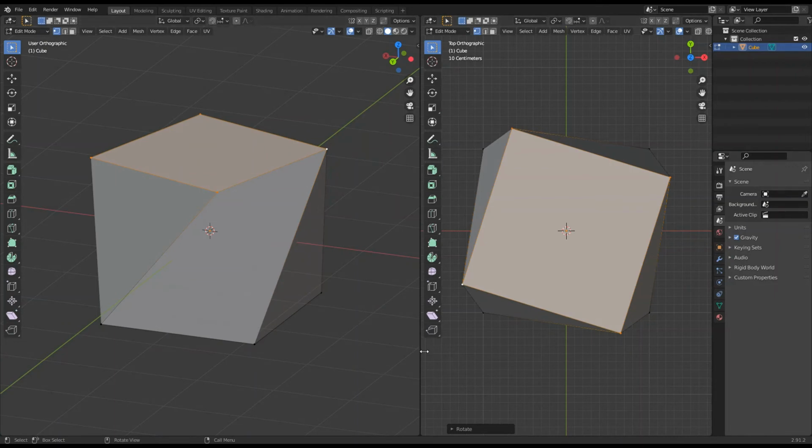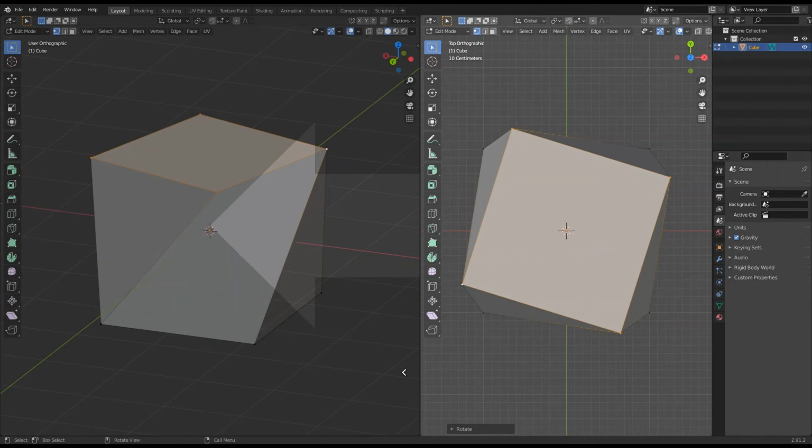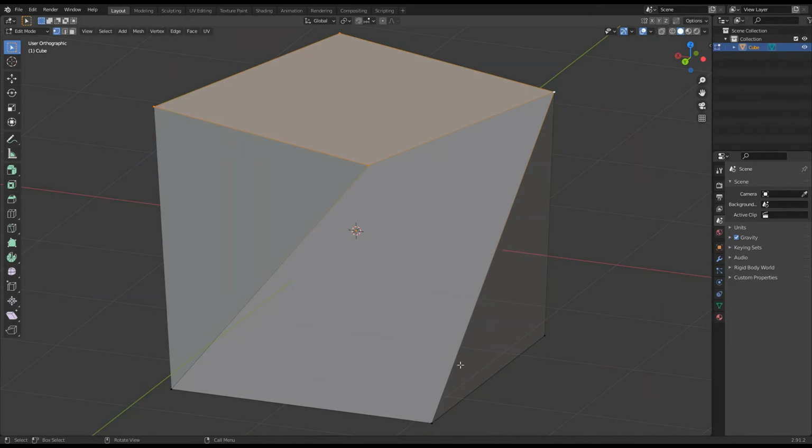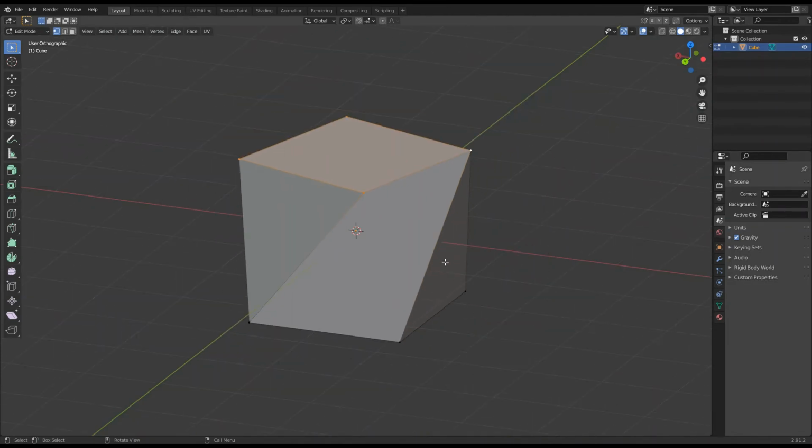And then if you're unhappy with it, you right click again, and it says Join Areas, hit Join Areas, and then that would take the right hand window over the left, or left over right. That's my preference. Okay, so that's how you can split your windows.